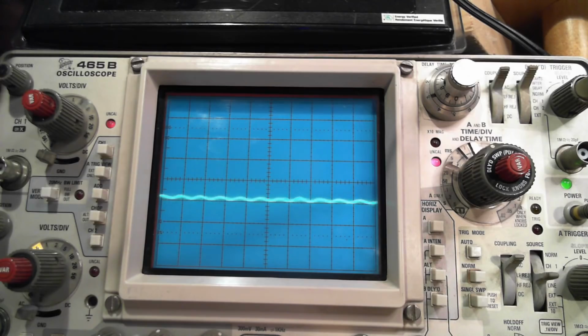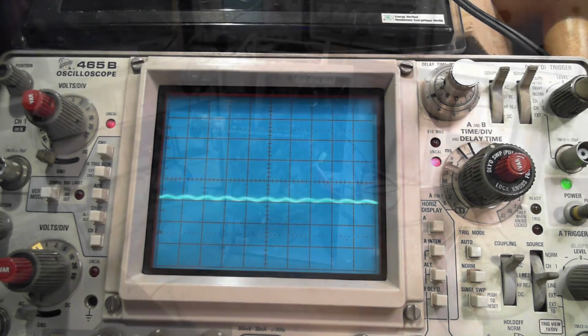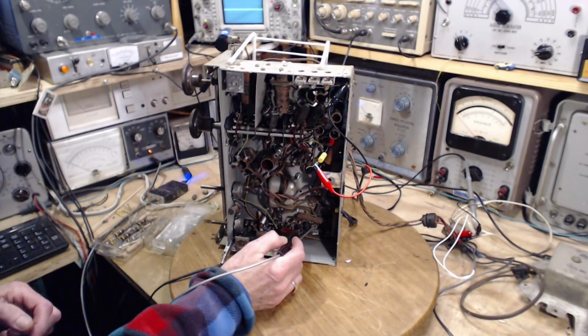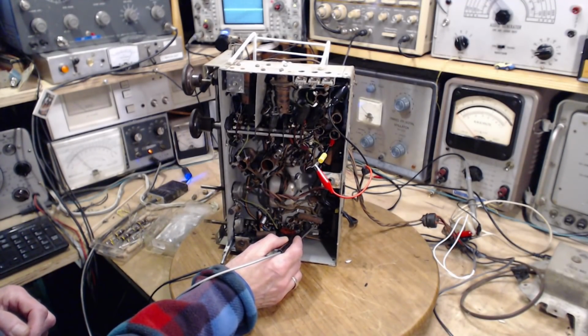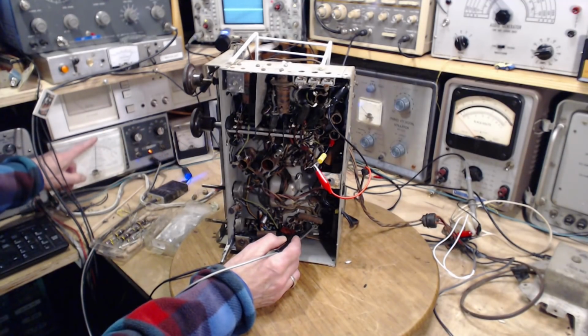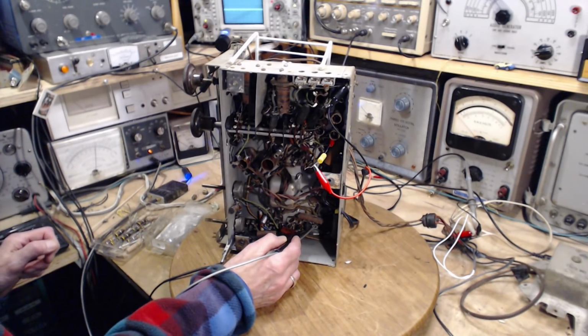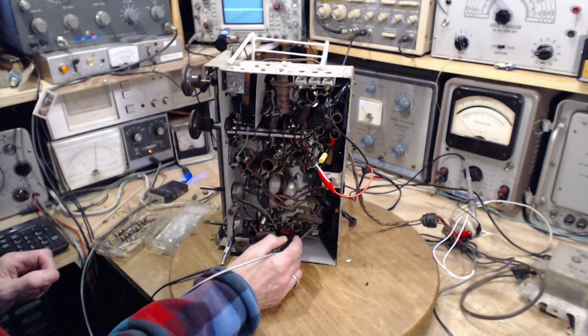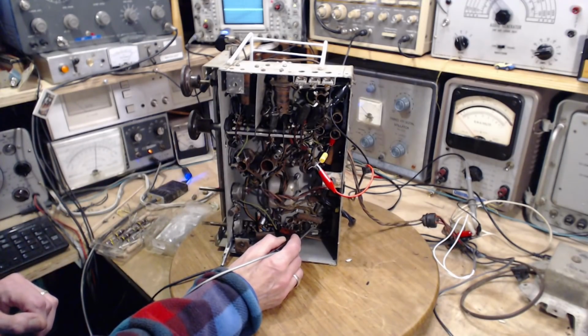I did measure with an ohm meter and didn't find a low resistance there. Oh, you're looking at the wrong thing there. Don't look at that. Look at this. Okay, voltage test. So this is on the 150, and we're coming up around 100 volts. Got 103 on the radio. That's probably depleting all these voltages a bit.